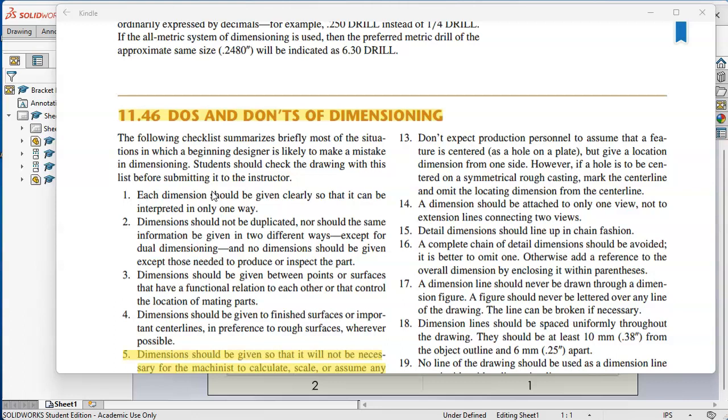So the do's and don'ts of dimensioning are in, I think I mentioned, the ASME Y14.24. Dimensioning, each of these is kind of a separate item with maybe a little bit more explanation. And again, these are suggestions. You have to put the eye on for your industry, for your company.